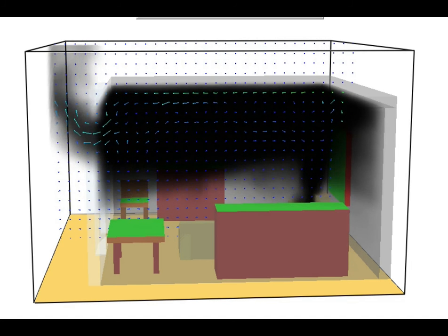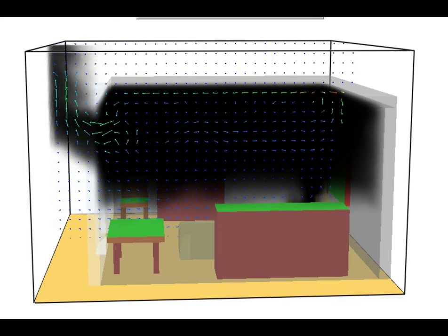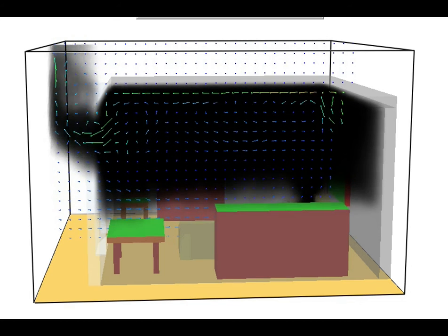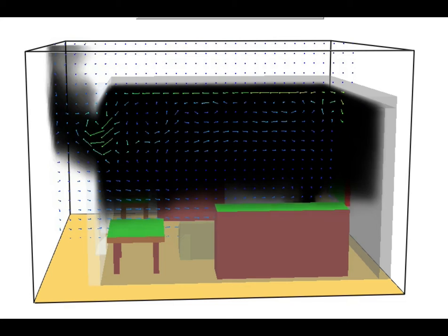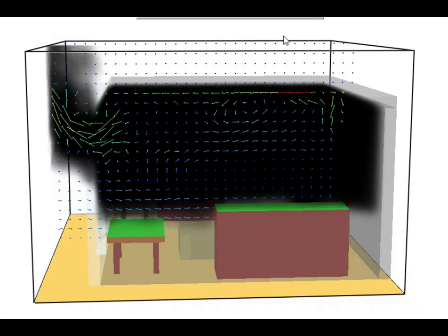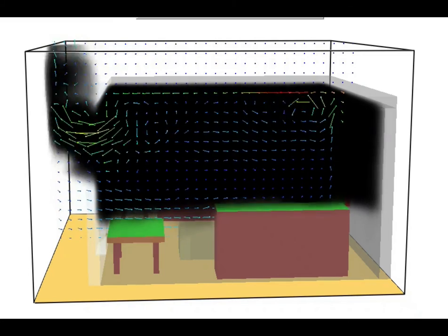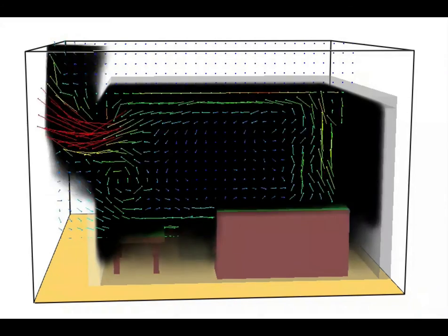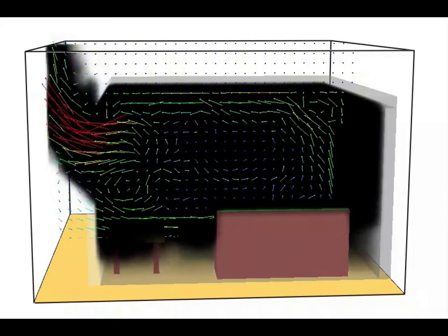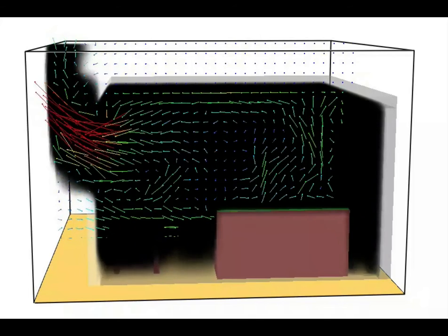Something else we can do with CFD is observe the movement of gases. During the initial moments of the simulation, we can notice the upper layer moving outwards with the smoke, while little movement is noticeable elsewhere. Further into the simulation, while faster movement is seen at the top layer, we can observe a flow of air moving through the bottom layer. During the final stages, while both previously mentioned movements have increased in intensity, a turbulent mixing of gases can be seen in the middle section.